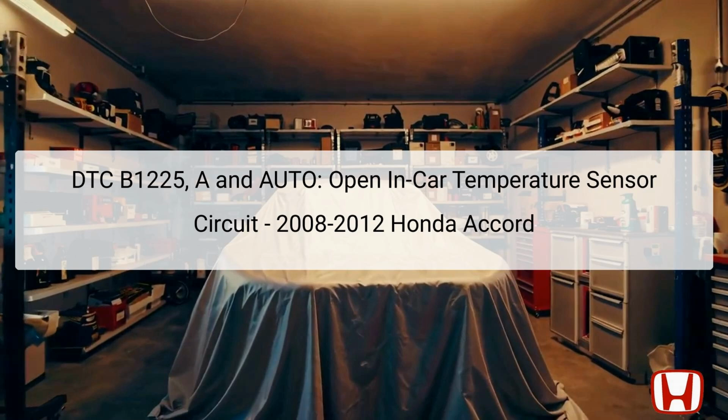accurate interior temperature readings. When there's an open in this circuit, the climate control unit may not function properly, leading to incorrect temperature adjustments. The diagnostic process is often initiated by using the Honda Diagnostic System, HDS, to read and clear codes. Failure to resolve the DTC can result in persistent operational issues with the interior climate control features, making it imperative for technicians to effectively troubleshoot and repair the root cause.